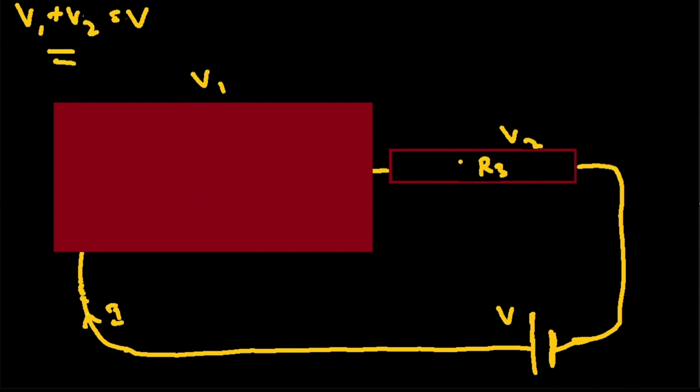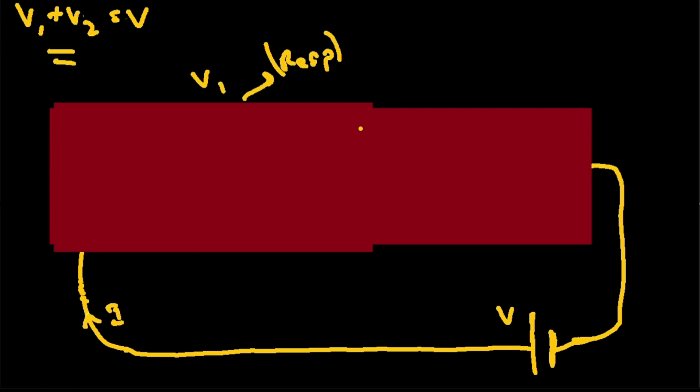Yeah, we can see that these two are in series. This I call R effective of parallel ones. These two are in series. So if I find the effective resistance of the series of these two resistances, then I can write R effective of this big circuit will be equal to R effective of the parallel ones plus the resistance R3. Then if I pass an I current through it, it has a potential difference of V, that is V1 plus V2. Try to find out this answer.